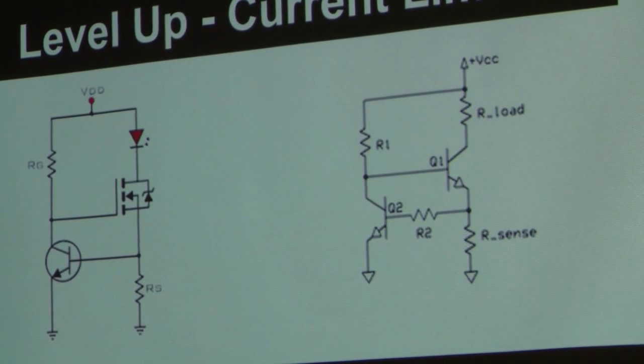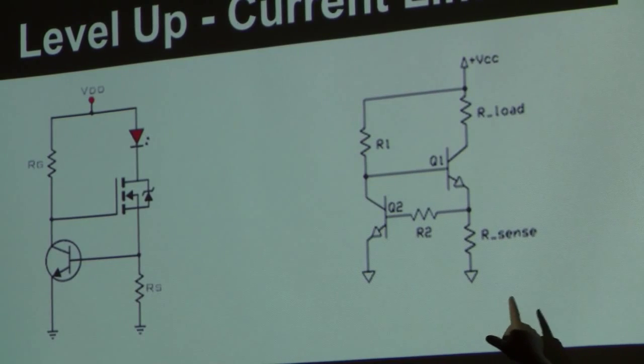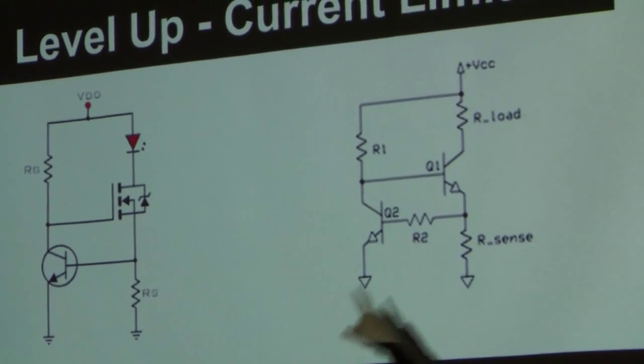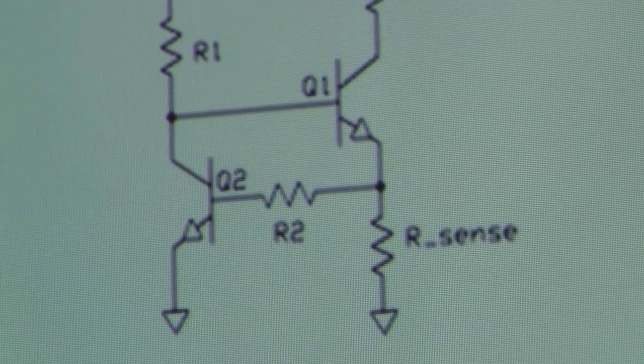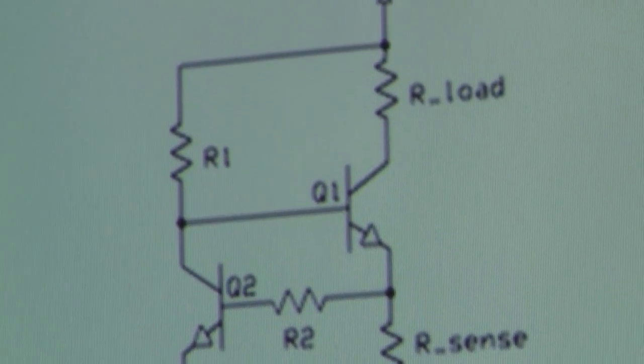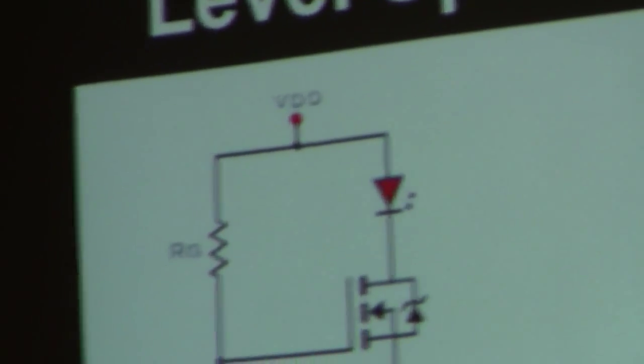This is the advanced level, so don't let this bother you if it doesn't make any sense. I only thought this one was neat because this and this are the same circuit, but using a BJT NPN for the switching element versus an NFET. This is one of the coolest circuits in all electronics in my mind.